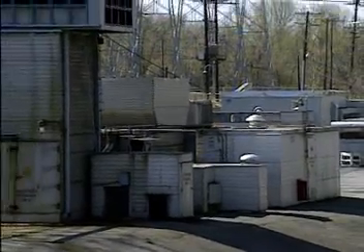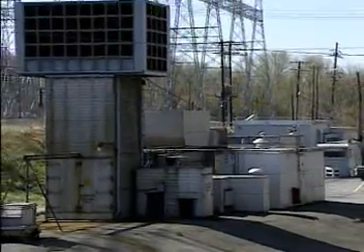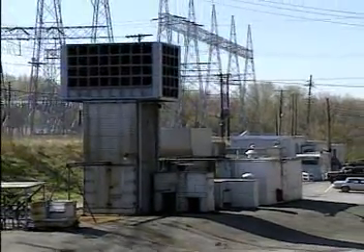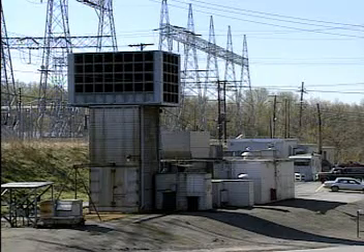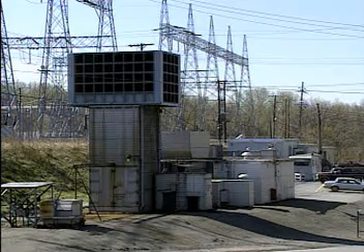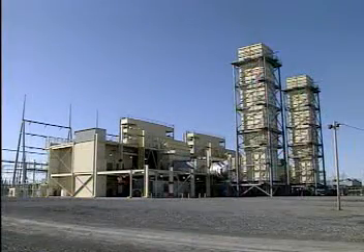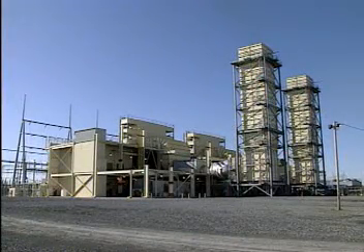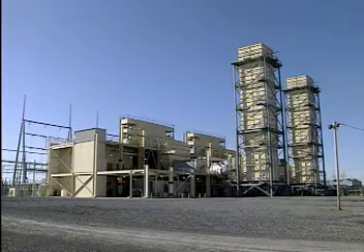Another advantage that many gas turbine units have is that all of the components are assembled together by the manufacturer. This means that after a gas turbine unit is purchased and delivered, only a small amount of work is required to put it in service. Gas turbine units also have some disadvantages. For instance, many of them are very loud when they're operating, and this may limit the locations where they can be installed. Another disadvantage is that they may be less efficient than fossil fuel plants.